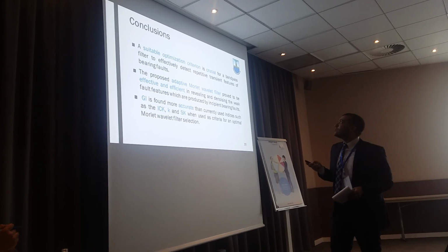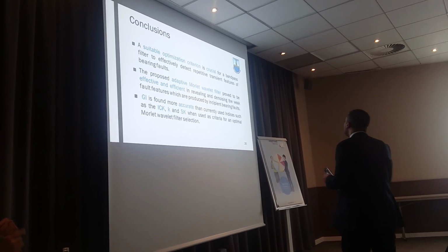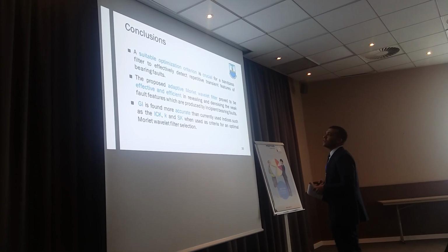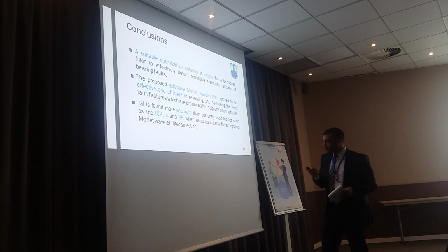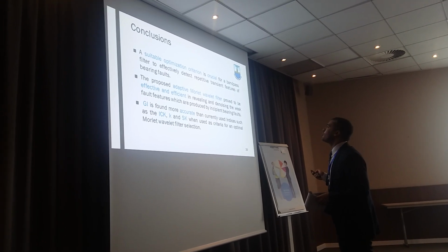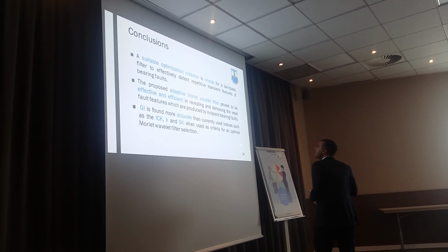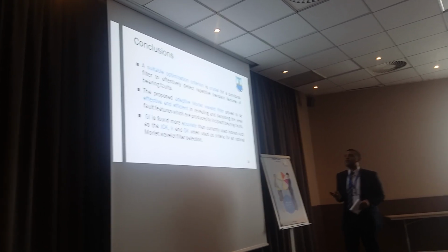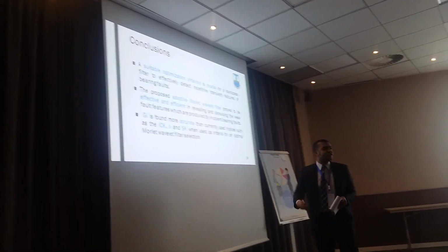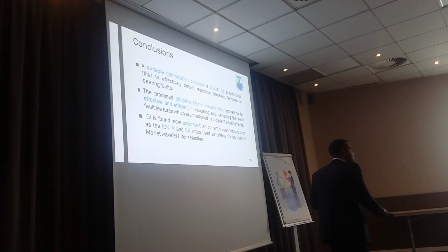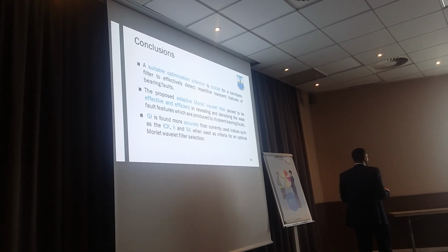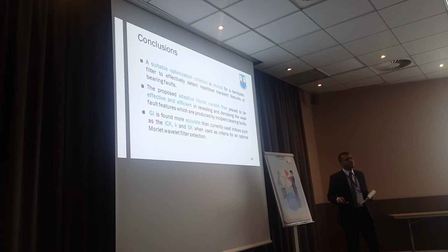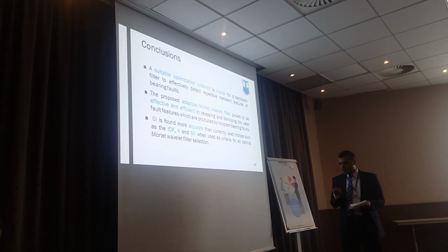Conclusions. A suitable optimization criterion is crucial in bearing fault diagnostics. The proposed adaptive Morlet wavelet filter proved to be effective and efficient in detecting early bearing faults. And Gini index was found more accurate and powerful than currently used indices such as spectral kurtosis, improved correlated kurtosis, and kurtosis when used as criteria for bearing fault detection.